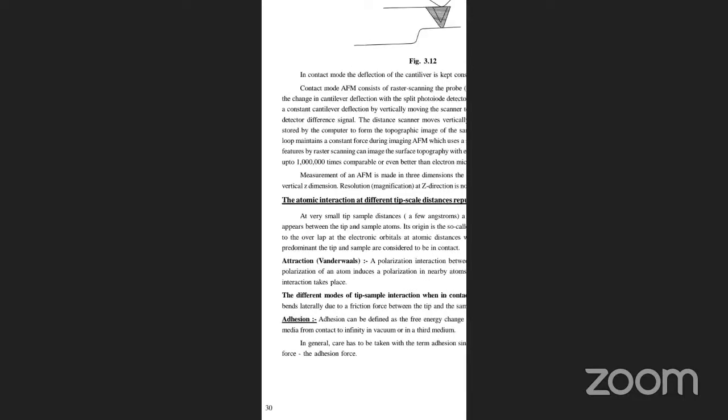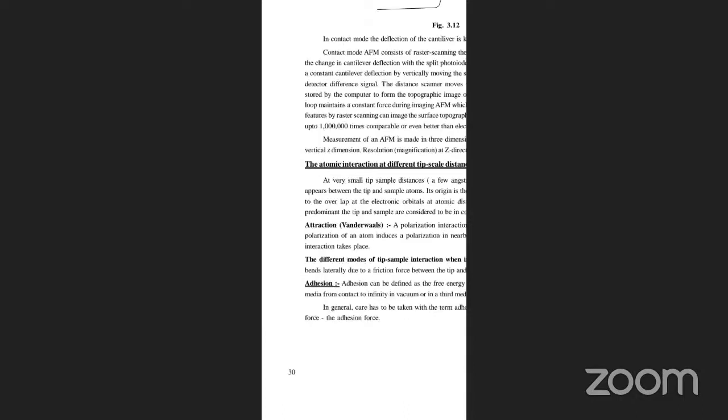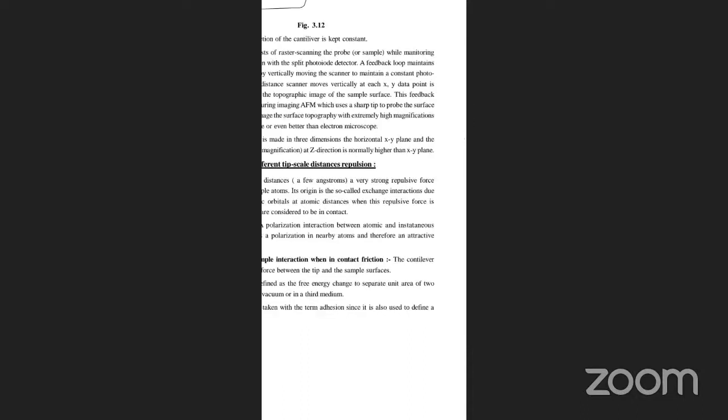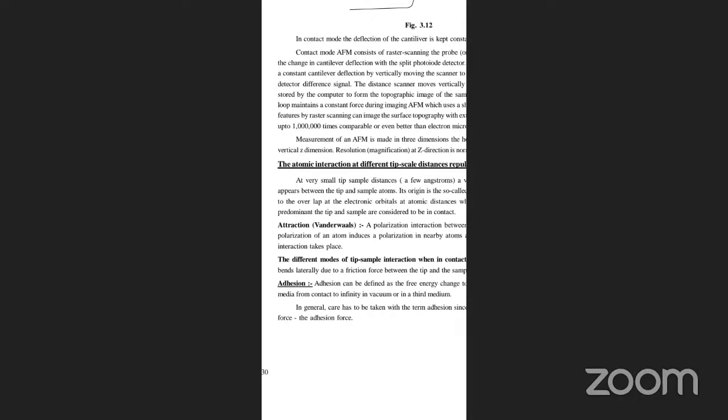The different modes of tip-sample interaction when in contact. Friction: the cantilever bends laterally due to a friction force between the tip and the sample. Adhesion can be defined as the free energy change to separate a unit area of the two media from contact to infinity in vacuum or in a third medium. In general, care has to be taken with the term adhesion since it is also used to define a force, the adhesion force.